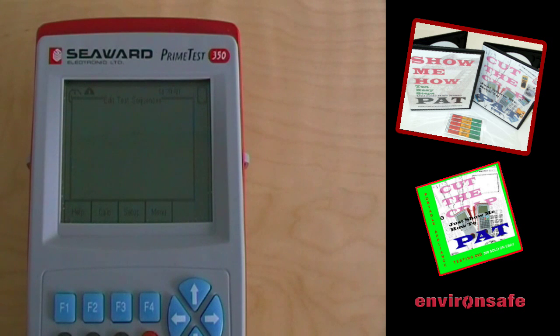F4 to edit test sequences, and this brings up the list of all the test sequences on the Primetest. Portable handheld IT class 1, portable handheld IT class 2, IEC mains lead 2 meter, 13 amp 5 meter surge protected lead, 13 amp 25 meter extension lead, 30 milliamp RCD, a portable class 1 PE current, portable class 2 touch current, IT equipment class 1